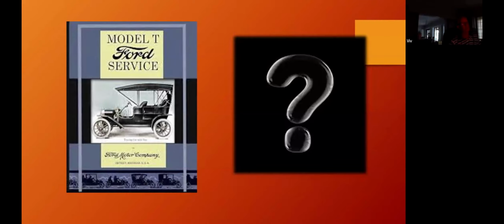Just another little thing, not Model T, but I've got the Talbot Darracq and I've got the Sunbeam, and they both have magnetos, and we were lucky to get a proper magnetizer for those, and pretty well what you described. We used that procedure. The magnetizer that I have access to is actually a Bosch magnetizer designed to magnetize Bosch magnetos.